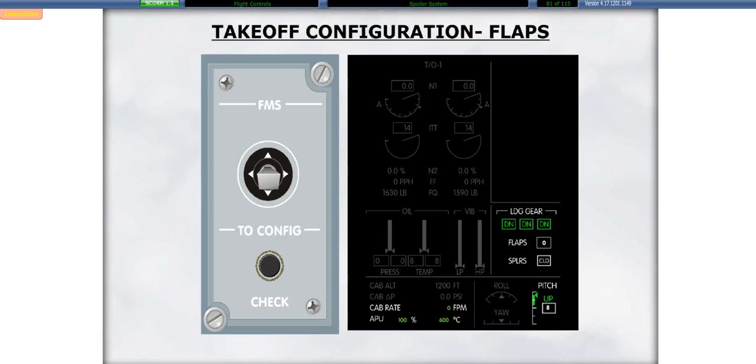If any thrust lever angle is above 60 degrees and the flaps are not in the appropriate takeoff position while the aircraft is on the ground, the takeoff flaps oral warning message is activated. In addition, the flap position indicator and box displays in red on the ICAS. A similar result is observed if the takeoff configuration button is pressed. At the conclusion of this audio, a takeoff configuration test will be automatically performed with the flaps out of their normal position. Takeoff flaps.